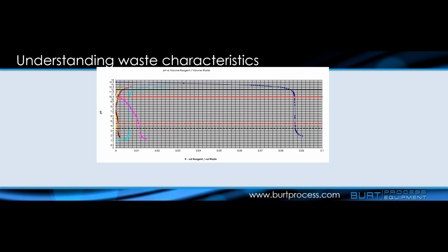The reason why you see this kind of alkalinity pattern here, as you get closer to neutral, to the midway pH, is because at that point your reagent chemistry is so much stronger than your waste stream. It gets very, very pronounced. But even here at the lower pHs, 3.5, 3, you start to see a very vertical peak. That's a sign of low alkalinity.